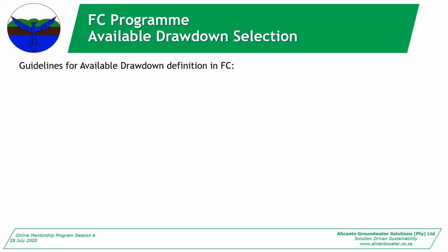Okay, there are many methods that you can use. There's one where you use a geometric mean when you don't have an idea of where the water strike is. So you just calculate a geometric mean when you have your static water level and the depth of the pump. It's the geometric mean between your maximum possible drawdown, which is your pump setting, and your static water level.